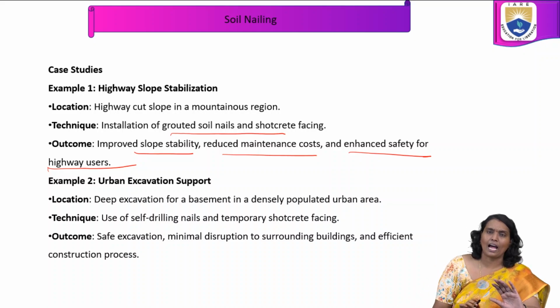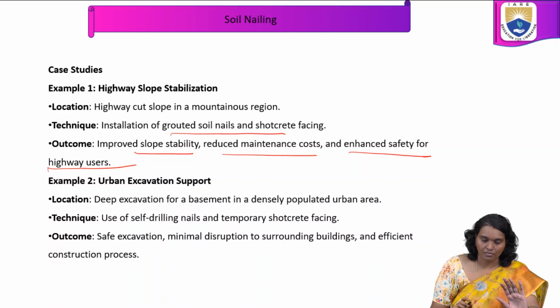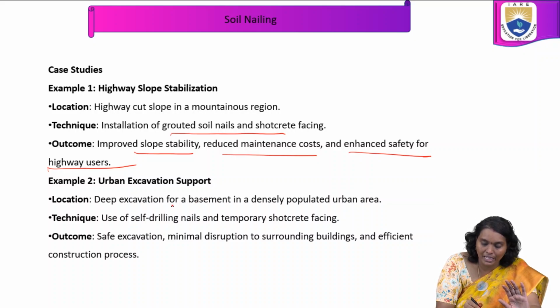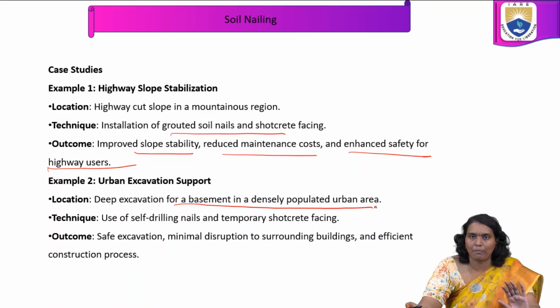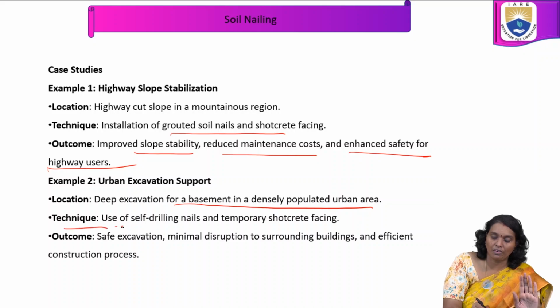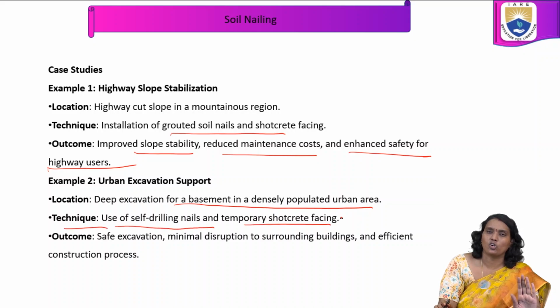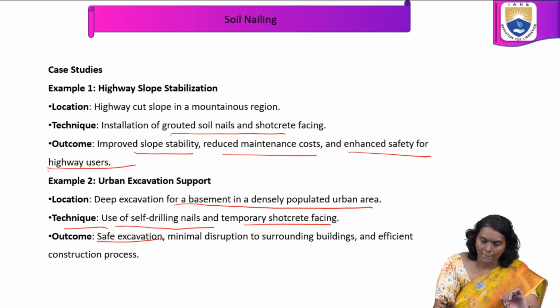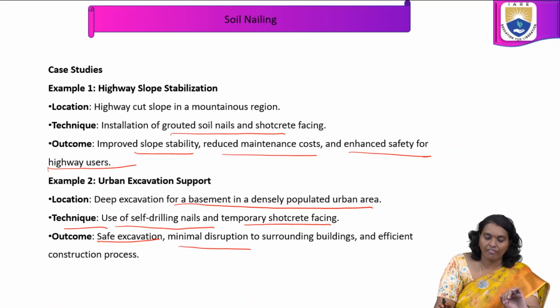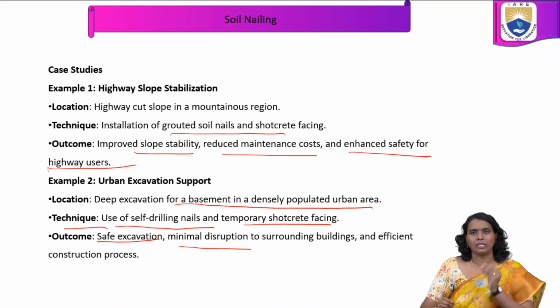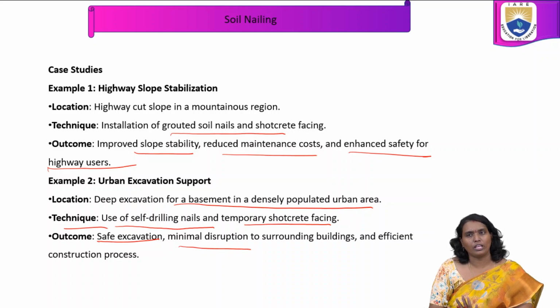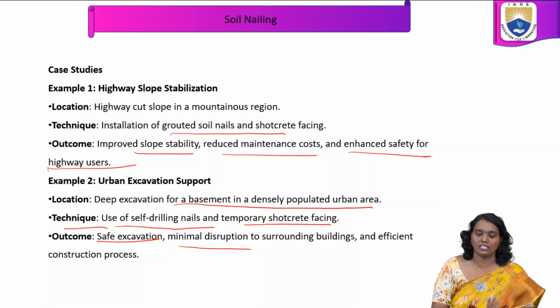The next one is urban excavation support. In a deep excavation for a basement in a densely populated urban area, we use self-drilling nails and temporary shotcrete facing. The outcome is safe excavation, minimal disruption to surrounding buildings, and an efficient construction process.